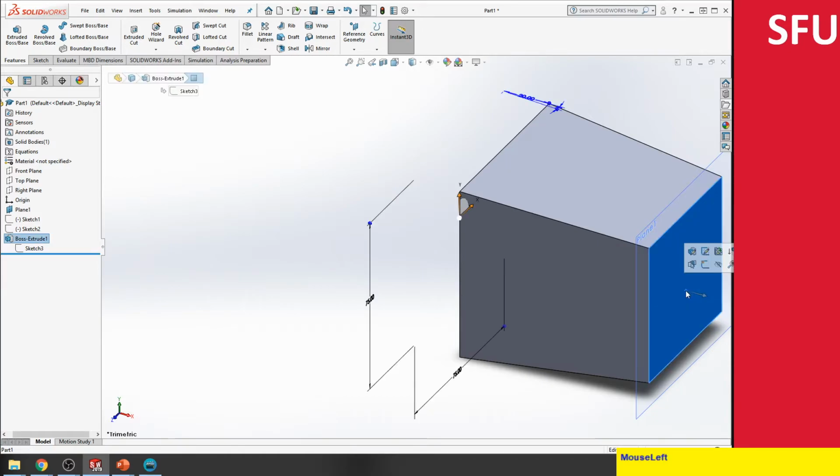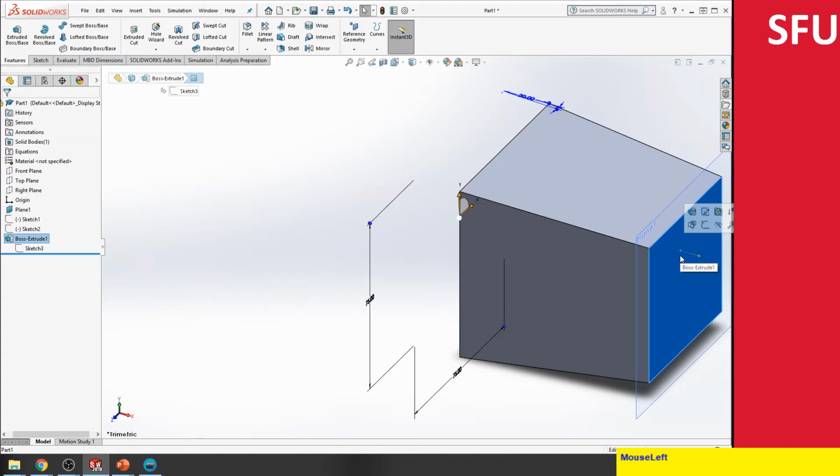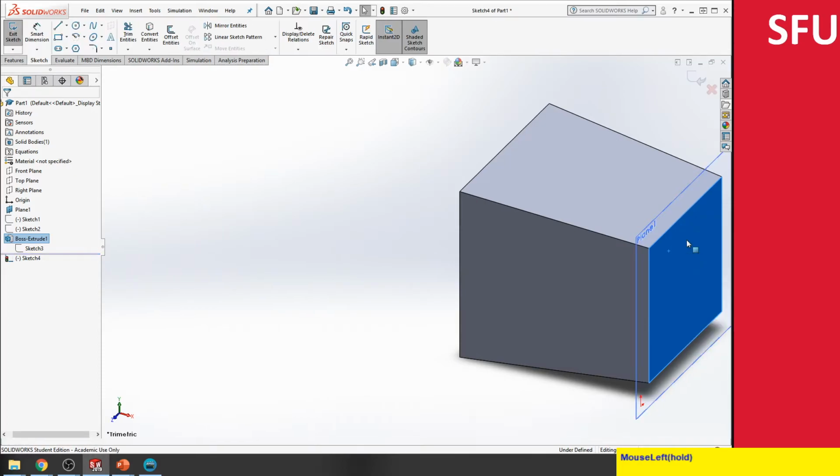Now I can create the sketch in one of two places. What I've selected now is the face of the extruded surface. This is different, and then I can similarly create the second sketch on plane 1 as well. Either would work, but I'm going to create it on this particular plane, and we right click here because it's a plane. It gives me the option of creating a sketch on that plane.